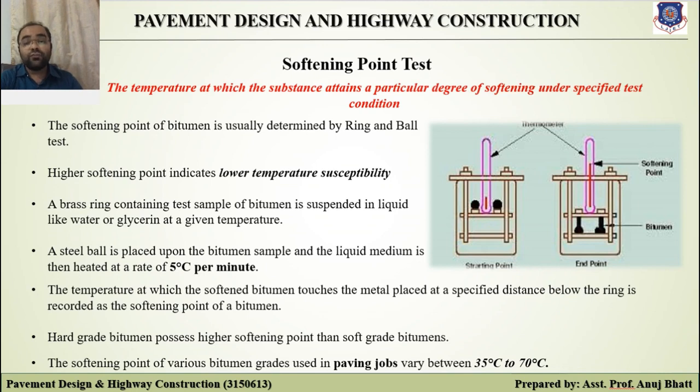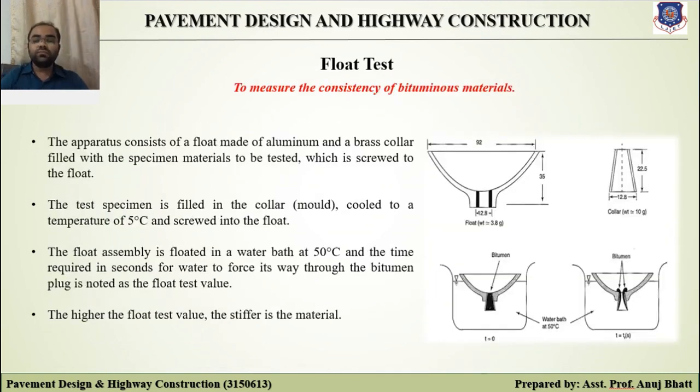Next is the float test. There is a range of consistency of bituminous material for which neither an orifice viscometer test nor a penetration test could be used to define the consistency of the material.